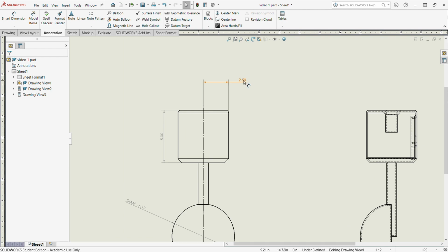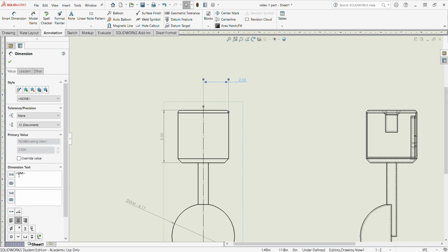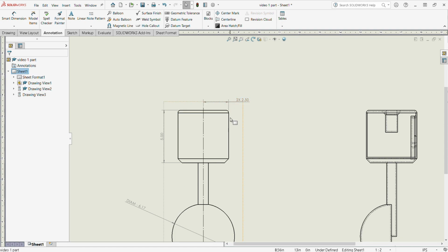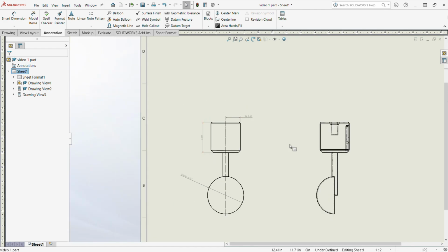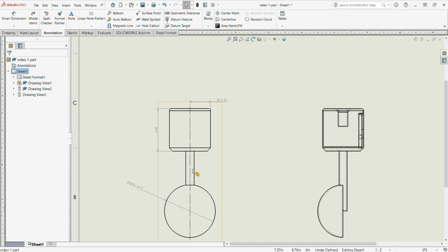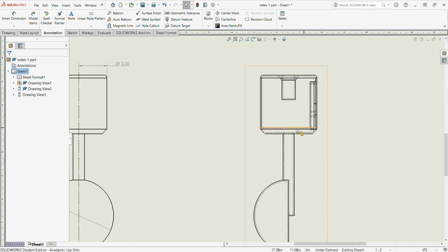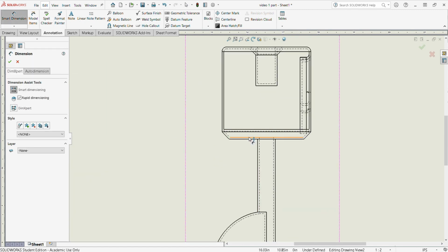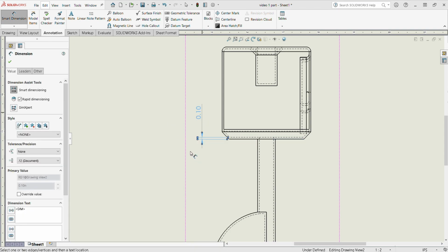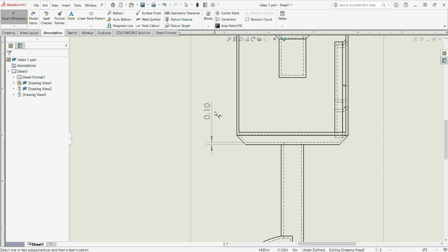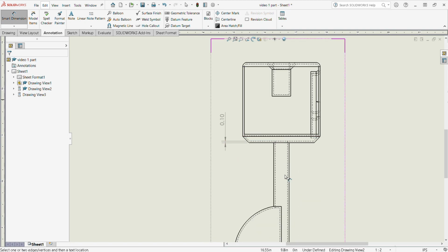And a good way to do that is to just put 2 times. So they're going to know, hey, this and this is the same as this and this, because this is a square and this is a circle. If it's a circle, you don't have to do it because it's a radius, so it's not a big deal. And then, by standard, you're going to want to do your wall thickness. If you want to put all around or just dimension it everywhere, it's up to you.